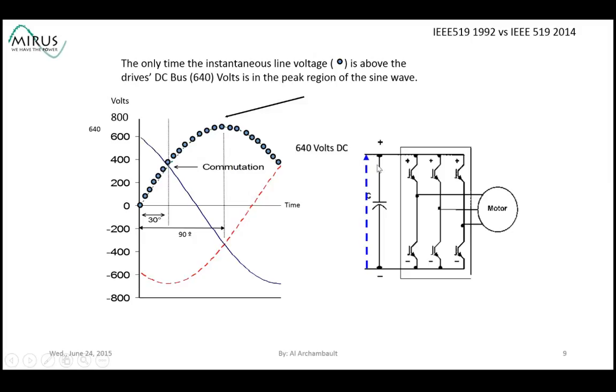So if I press the start button and the shaft starts turning, this voltage is going to decrease quickly. So it's already dropped to, say, 600 volts. So now I've got this sine wave voltage coming in. Let's assume we've got diodes here. When in time is the instantaneous value of this half sine wave going to be equal to or above 600 volts? Well, it's not here. It's obviously going to be up near the peak. And 1/2 cycle on 60 hertz is approximately 8 milliseconds. So the only time I have high enough voltage to overcome the DC bus voltage is going to be up in this peak.